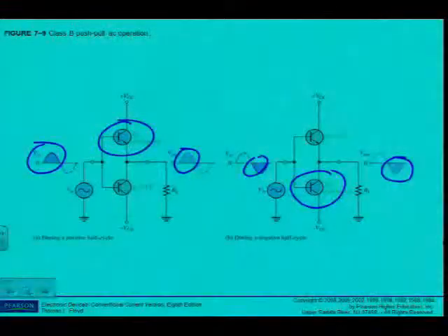Can you remember, the transistors aren't switched on. So we need that 0.7 volts for both transistors before the base emitter junctions are forward biased and the conditions are met for linear amplification. Alright, so although the condition is much better, we now have a class B push-pull amplifier. It's not only the positive alternation, now it's the positive and the negative alternation. But I still have a problem.